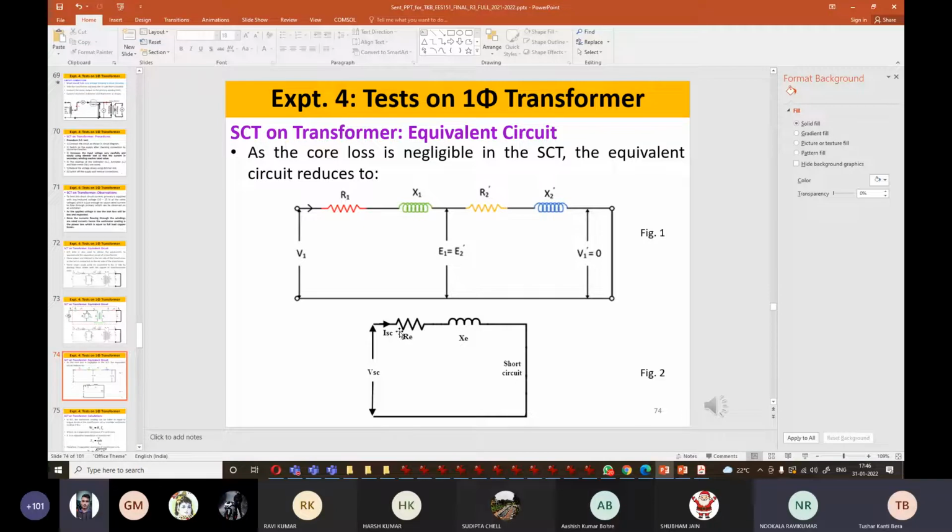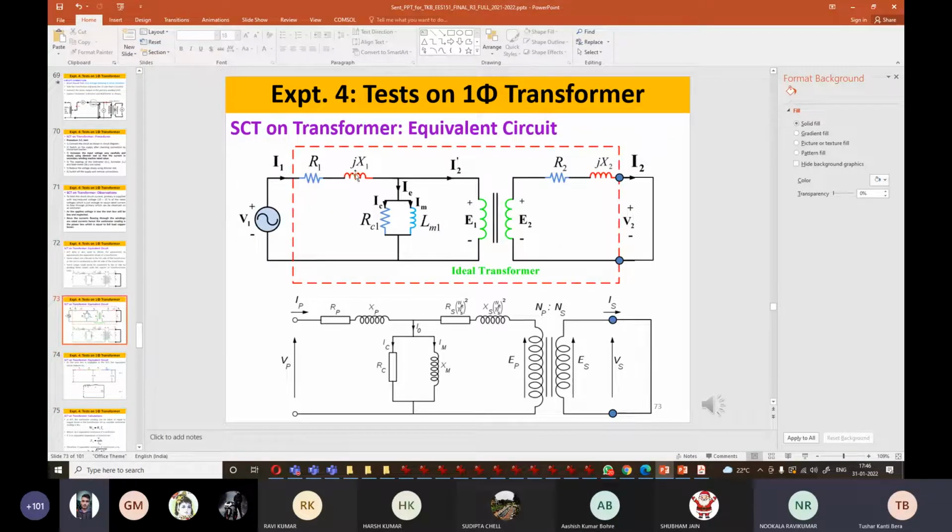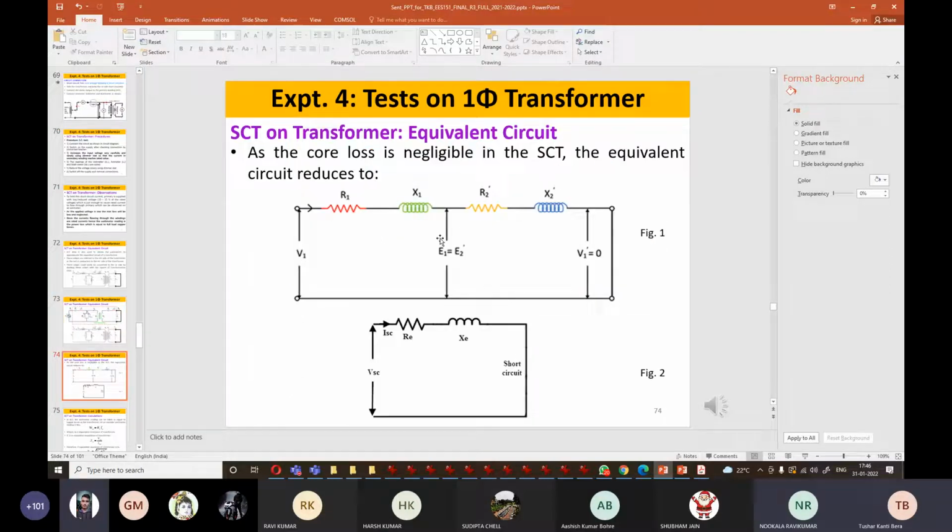And whatever is there in the secondary, the transformer is transferring some power by induction also. Whatever current is entering here, due to that current some flux is generated, due to that flux voltage is generated, and due to that voltage some current is flowing. So whatever power is consumed in this winding is part of the entire power, because power enters only through the primary winding. So whatever power is entering is the total power loss, meaning primary copper loss and secondary copper loss. In the secondary the power is not coming by magic, it comes from the primary. For calculation all parameters have been referred to the primary side, that's why we can use all the primary winding readings.